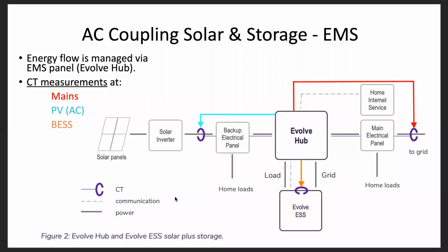That'll maintain in off-grid mode as long as there's available sunlight and the batteries are being charged on a daily basis. Obviously, it's a balancing equation between the loads and the generation. You want to be able to generate enough power to serve some of the loads, but also to charge the battery so that those loads can be served by stored energy throughout the night till the next day.